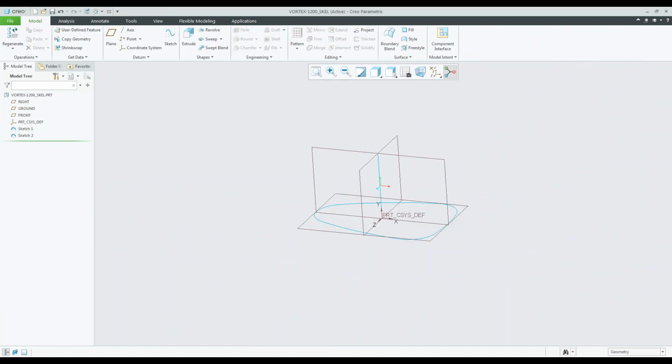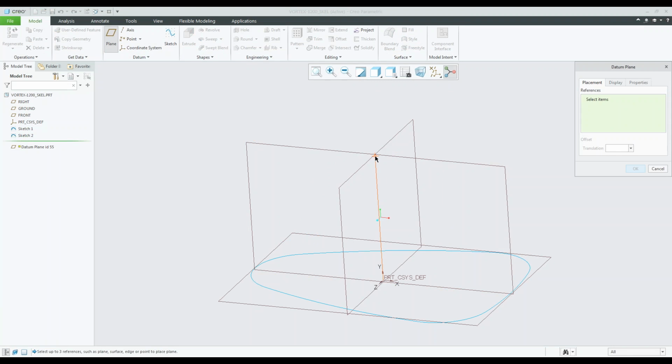So here we have some critical size dimensions that we are including in the skeleton. You can also start including datums for mounting locations, or if you're trying to incorporate motion for your skeletons as well. So for example, if I wanted to create another reference, a tilting plane reference for motion of the fan itself, I can do so. Let me start creating a plane that's going to be at the top of this vertex, as well as parallel to this ground instead.